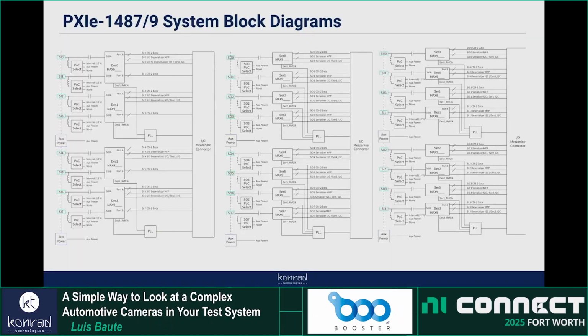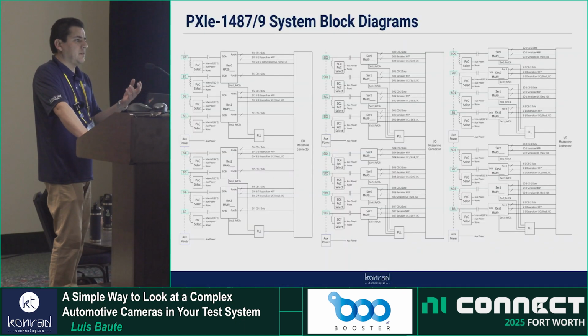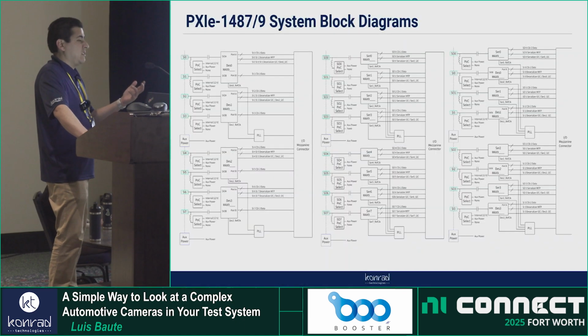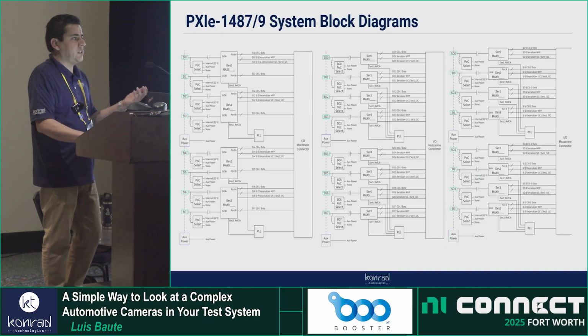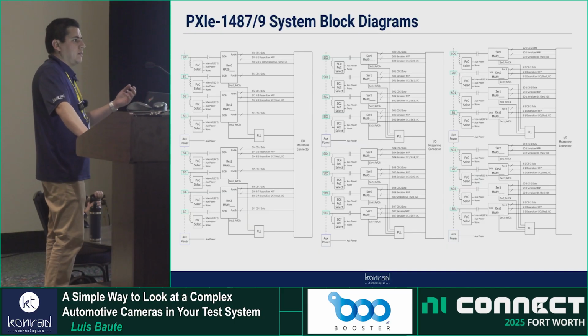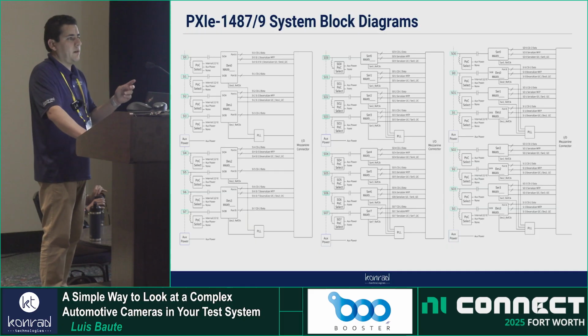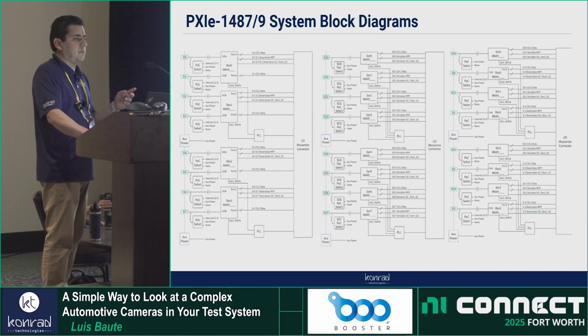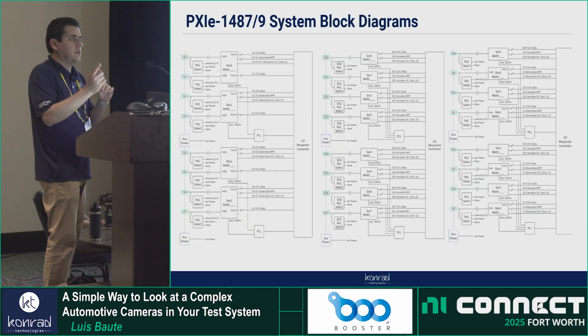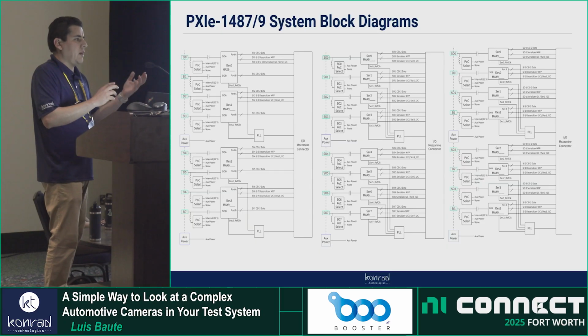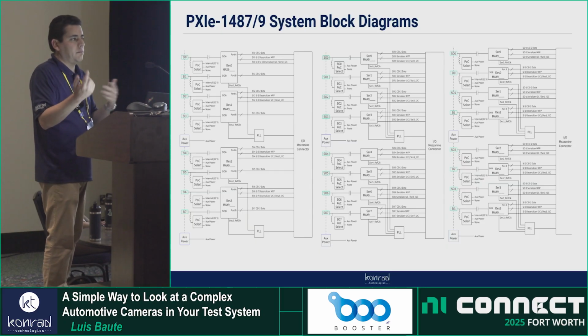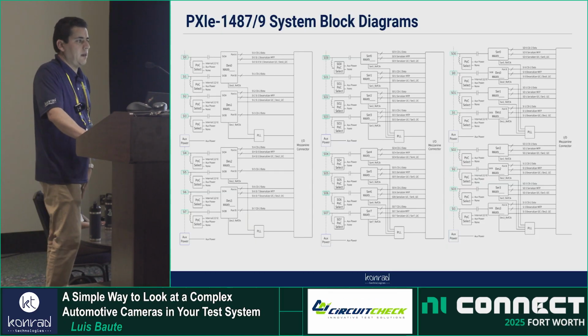Okay. And to explain a little bit about the aliasing, it's because the customer wanted to test the cameras at their default state, which is not changing the I2C device address. So since you have 2 cameras in the same chip, the chip needs to know which camera it is talking to. So then we do the aliasing, so the deserializer knows which address you are talking to, and the cameras don't know that they are 2 in the same place and they have the same address.